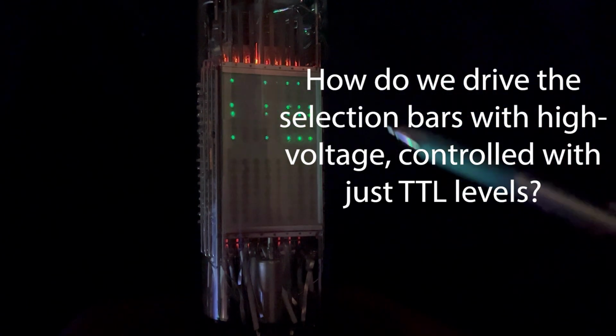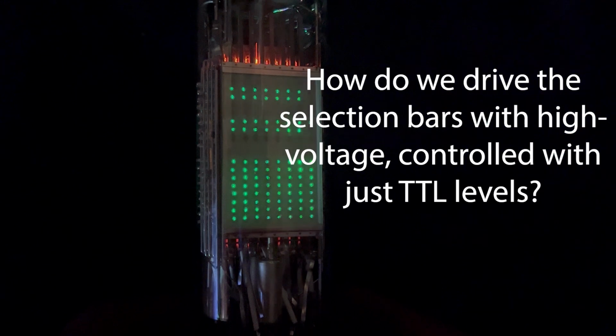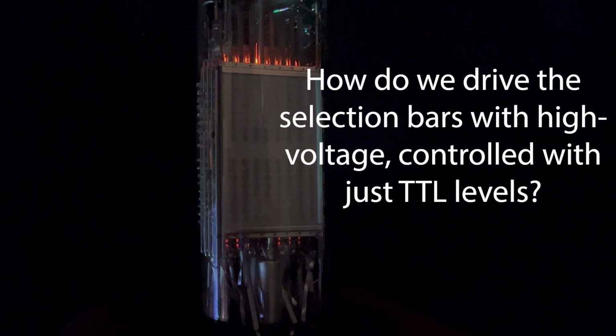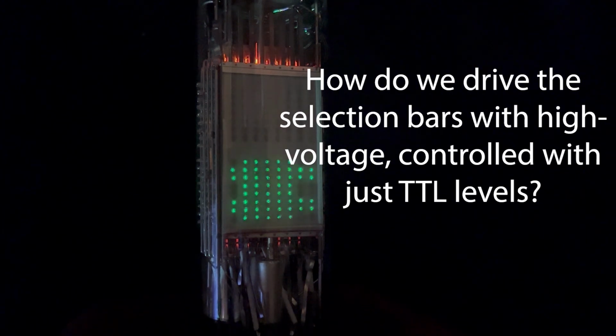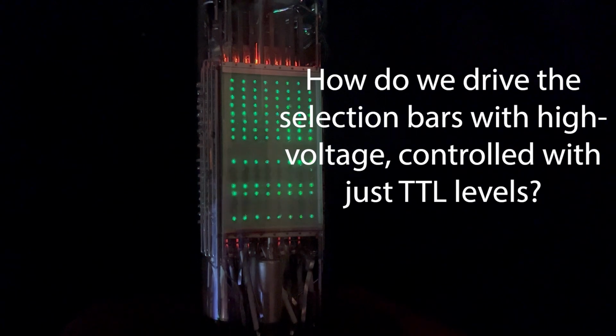Finally, I'm going to go over a circuit that would allow me to drive these selection bars either to 0 or minus 250 volts with just simple TTL signals. My microprocessor is going to control this, so I need a driver circuit which will switch between 0 and minus 250 for each bar. So let's get started.